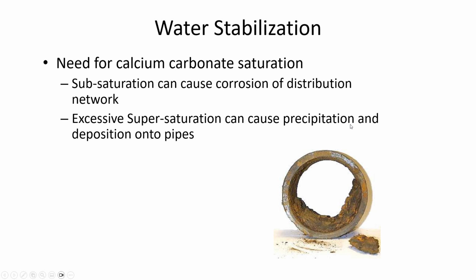Disinfection is one of the last steps in the water treatment process, but there are some things that they have to do depending on the location. There are cases where the water may be corrosive because it has so little mineral content that it could cause pitting of the pipes that are carrying water towards the people who are consuming it. And so sometimes after water treatment is completed, they'll have to add additional minerals to it.